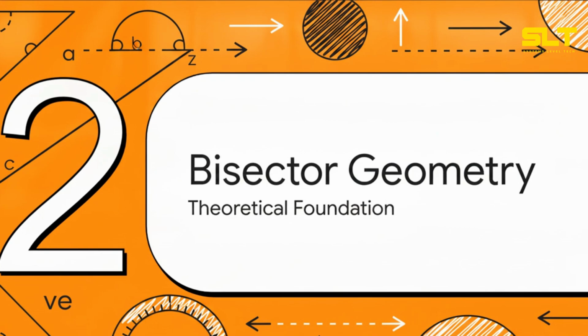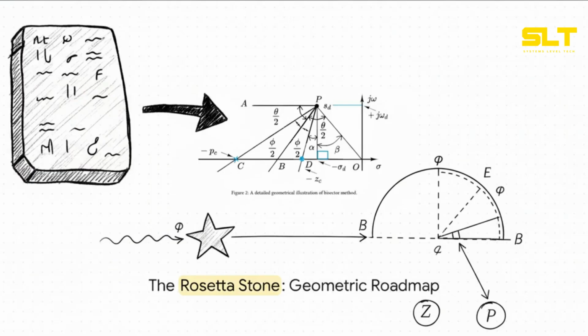Section 2, geometry of the bisector method. Now, what's really interesting here is the geometric roadmap of the bisector method. It acts as our Rosetta Stone, mapping out absolutely every variable we are about to solve for. Point P up at the top is our desired pole location. The method works by drawing a line from the origin directly to our desired pole, and then bisecting, meaning perfectly splitting that angle, to symmetrically place our compensator zero, which we call Zc, and our pole Pc.